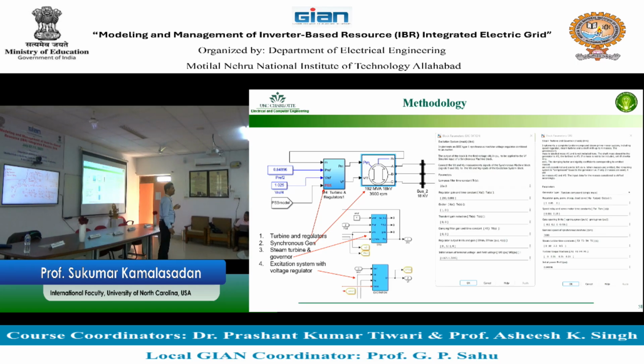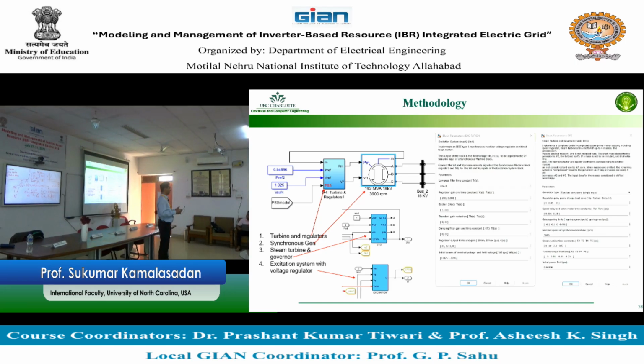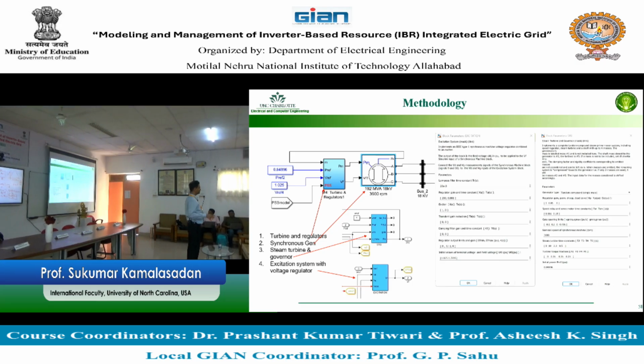And that doesn't really need to be a fancy, very large system. A 9 bus, 13 bus, unbalanced system, all three machines. One is a voltage source, another one is a synchronous generator. That's enough. And then you just change to IBR and see what happens. Forget about even IBR, just put all the generators there.